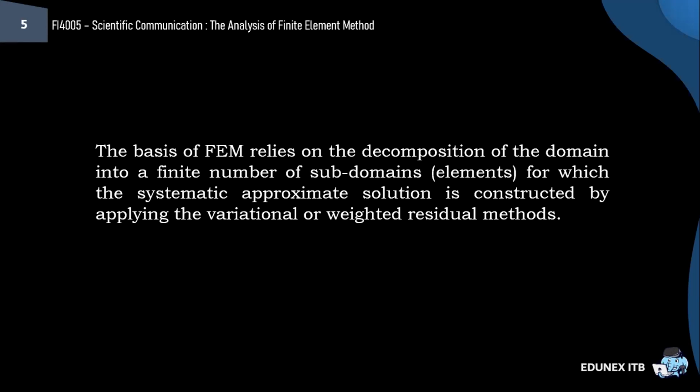In effect, FEM reduces the problem to a finite number of unknowns by dividing the domain into elements and expressing the unknown field variable in terms of approximating functions within each element.